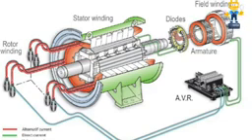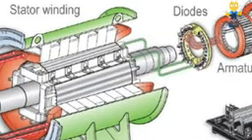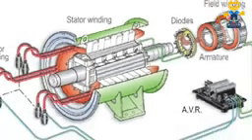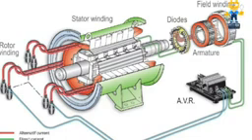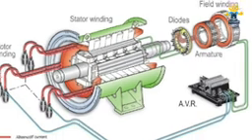This three-phase AC power connects to our diode plate, which has a three-phase diode assembly that converts this three-phase AC power to DC, and this DC power goes to our main rotor.